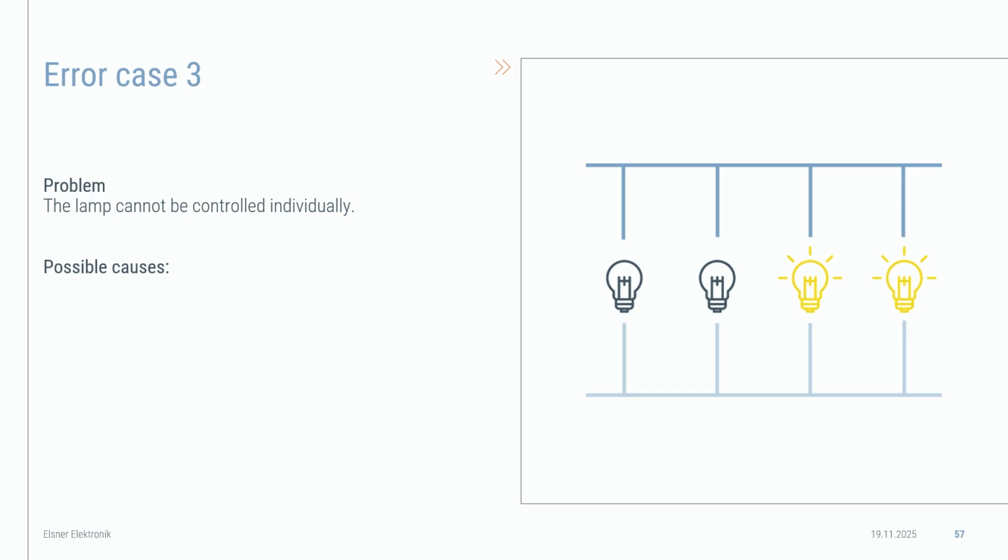How can this happen? It's usually if you have an installation site and then you had some lights removed, or you had a new redesign. So you removed some lights, you put them in the storage area, and then after a while you got those lights and placed them back in the system, and it's still addressed. It holds all the information it has, but you have a new device which has the same address, and this will cause the devices to behave at the same time.